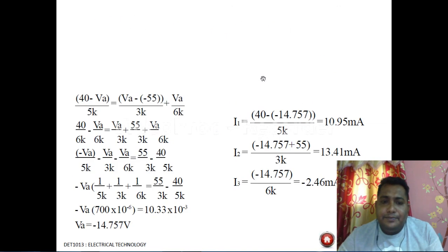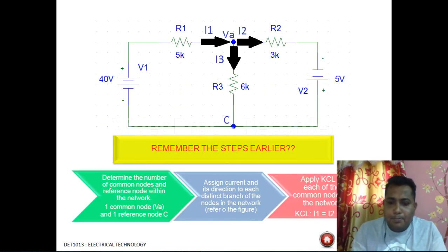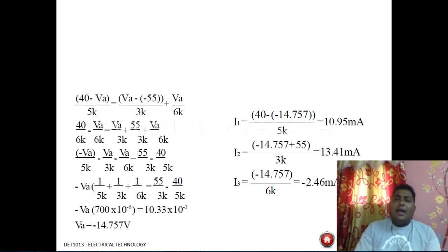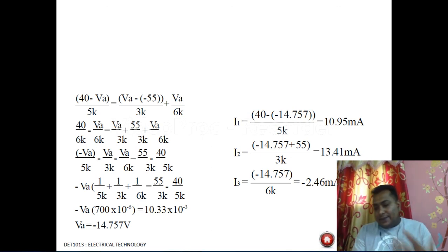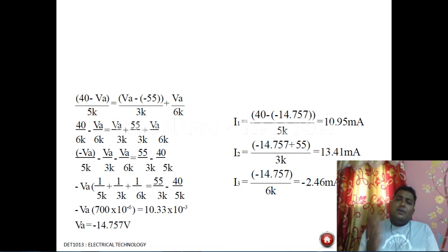What is the voltage over here? Yes, this is the formula. So use that formula and transfer it into the voltage equation. And after solving this, you will very easily understand how we are going to solve this KVL, KCL. Those two theorems are very simple to understand. So first write down the current equation, then convert that current equation into the voltage equation, and then find out the node voltage. And after finding out the node voltage, you can very easily find out the particular current value. And if we know the particular branch current value, then we can find out any branch voltage. So this is all about the KCL.